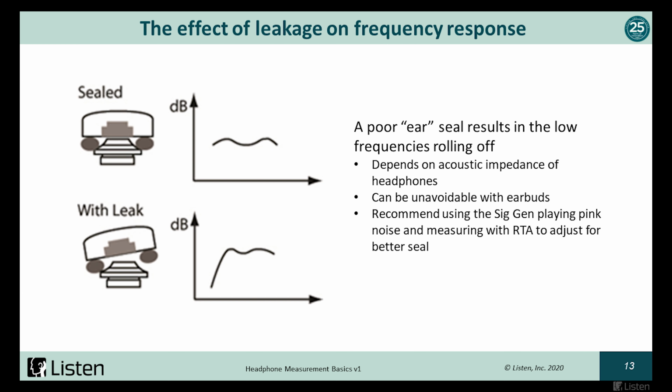So speaking of seal, let's talk about the effects of leakage on the frequency response. A poor ear seal results in low frequencies rolling off. I think that's pretty obvious, because now the low frequencies are allowed to leak out and not just directly coupled to the ear. As I mentioned before, it depends on the acoustic impedance of the headphones. An open back headphone won't be as sensitive to this as a closed back headphone.